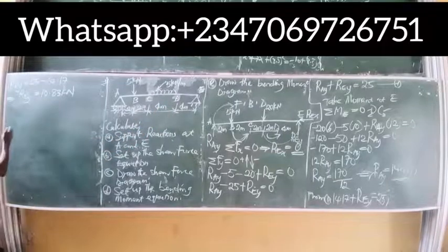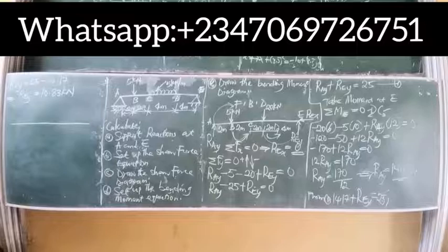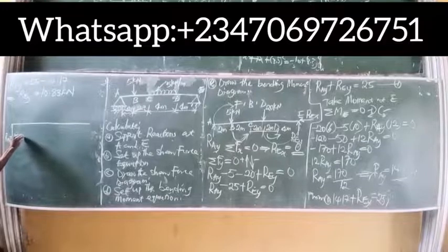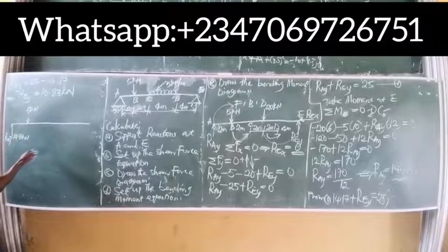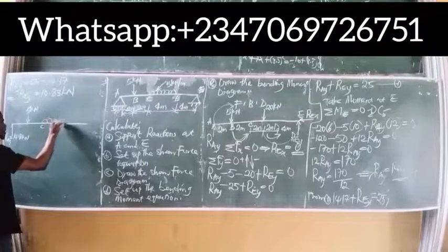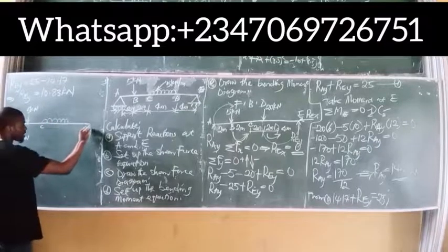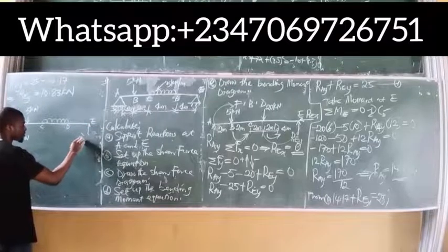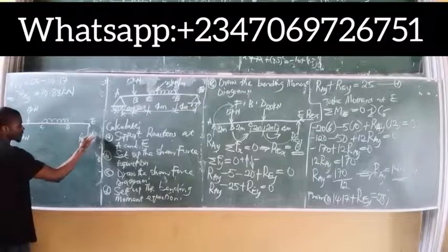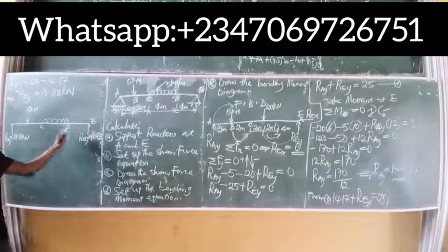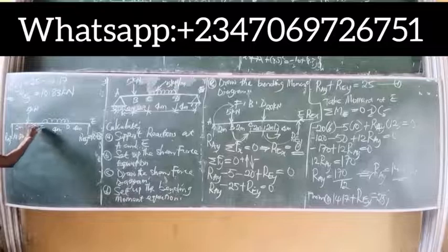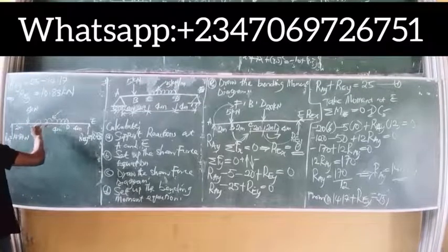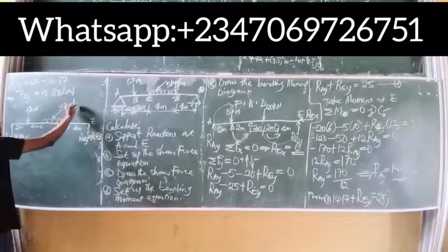So if we do that now, we bring back the beam. We know support at point A, RAY, the value gave us 14.17 kilonewtons. And at point B, we have a downward force there, 5 kilonewtons. Between C and D is a UDL. So put back the UDL, very, very necessary. Then we'll have REY at point E, REY gives us 10.83 kilonewtons. So distance apart 4 meters, 4 meters, 2 meters, 2 meters, right? Yes. And the value of the UDL will remain 5 kilonewtons per meter.